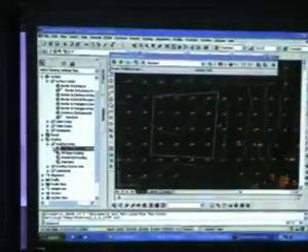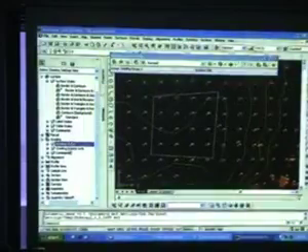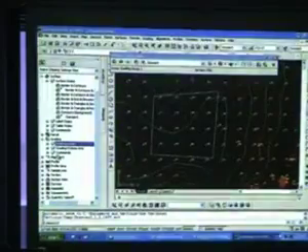Completely customizable. I'm just going to leave this as is. So grading styles is for the display of your slopes. Grading criteria sets is how the slopes are defined.